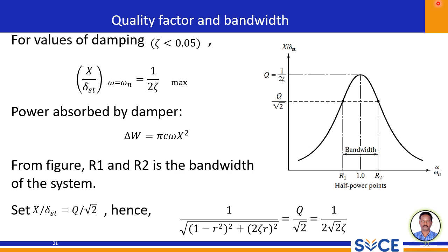In summary, this slide highlights the significant impact of low damping on resonance behavior. Low damping results in high amplitude ratios at resonance, a high Q factor, and a narrow bandwidth. These characteristics are important in various applications where the resonance needs to be either enhanced or avoided.